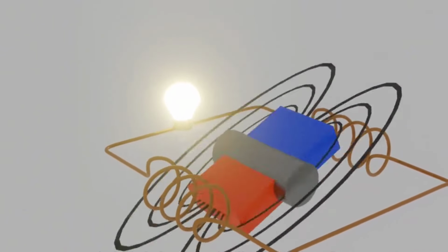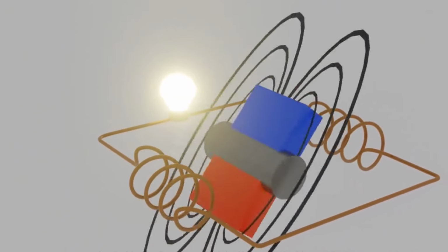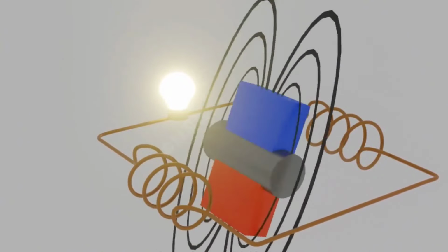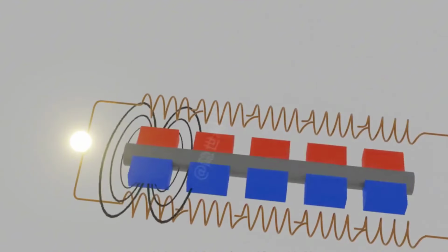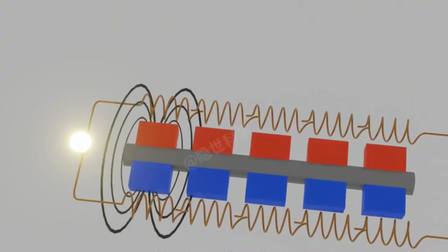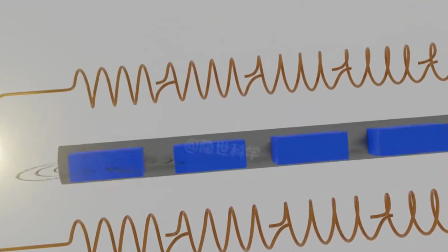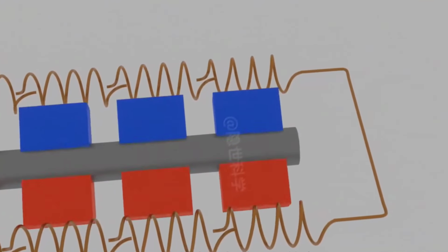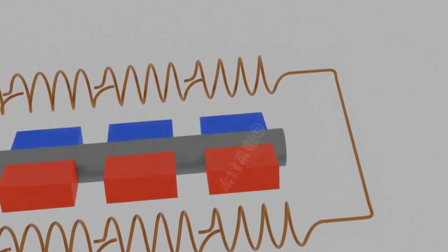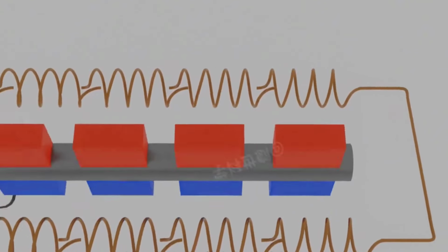In order to generate enough electricity, some engineering design is required. To increase the amount of electricity that can be generated, for example, the number of magnets and stator coils can be increased, but this will make the generator quite large. Increasing the rotating load, therefore, reduces the working efficiency of the generator. So how to generate high power while keeping the generator compact?